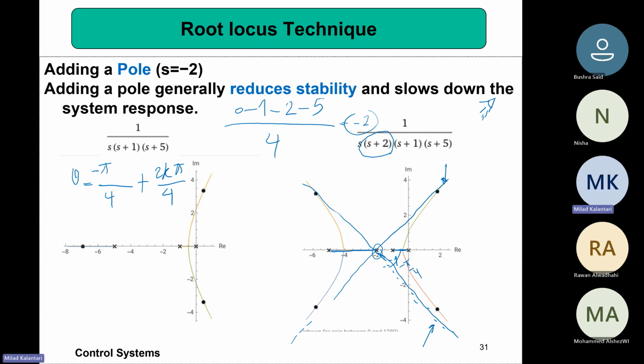So when you have a second order system, you will have only two asymptotes at the end, which will be something like this. It usually starts at some place, and one is on the real part, the other one is an imaginary part. So most probably if the real part is okay, then the imaginary is not supposed to go to the right side. It's just vertical. So it means that for the second order system, usually it should not be unstable when the k goes high.